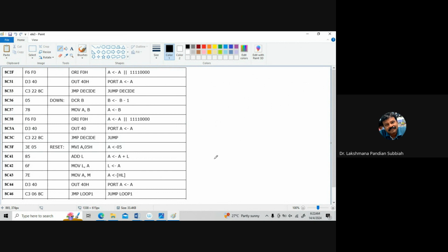Accumulator, in that accumulator we are getting now B6, right? So B6 is here, B is 1011, then we are having now 6 is 0110, right? So this is 6, then this is 1, right? So that one is here once. So what we need to have, that one, is to reset the corresponding second floor light, right? So the second floor light is now reaching that LED, then the second floor light we have to reset. So for that we have to send this data to the port A.